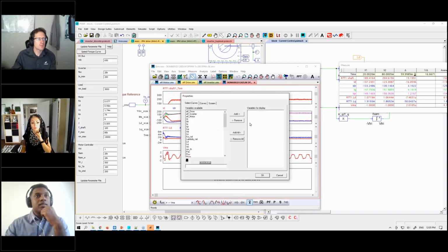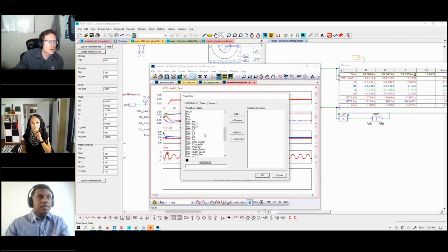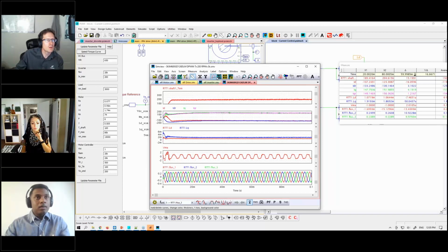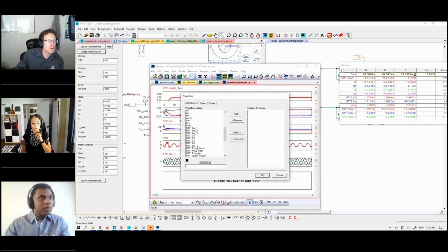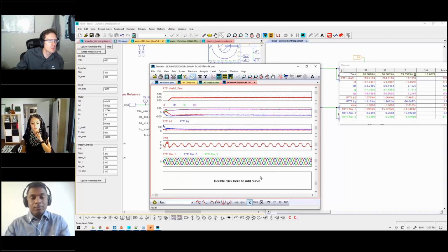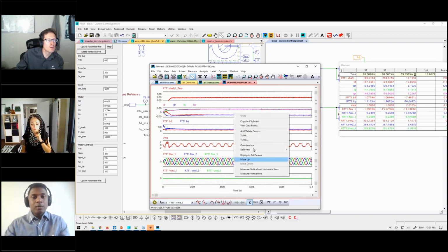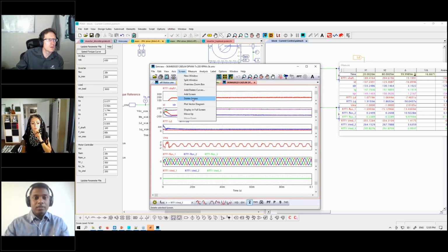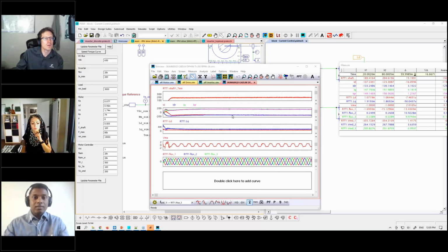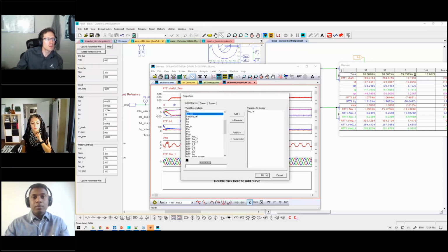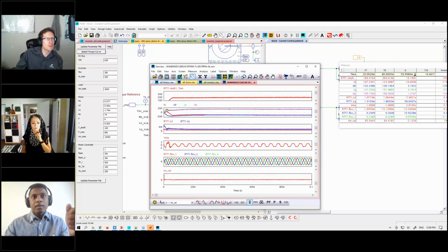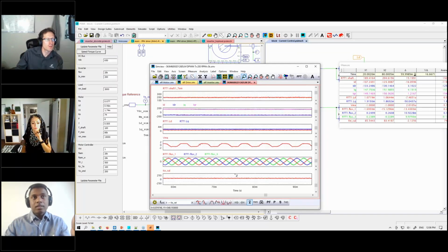I see there's a couple more questions on the inductances from the same gentleman. Are the DQ inductances incremental or apparent? PM machines have PM flux in the D-axis. To remove the impact of the PM flux on inductance measurement, what we usually do is D-axis is incremental inductance and the Q-axis is apparent inductance. On the RT model, I don't think that's an option to change.